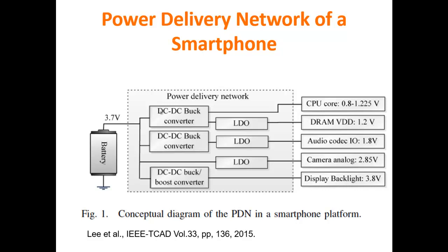If the computational load is smaller, because the CPU has to do a smaller number of tasks or smaller tasks, then you can reduce the clock frequency, and if you reduce the clock frequency, you can also reduce the supply voltage. And the only reason to further reduce the supply voltage is to save power consumption, because, if you remember, at a given clock frequency, the dynamic power consumption is proportional to the supply voltage to the power of 2.